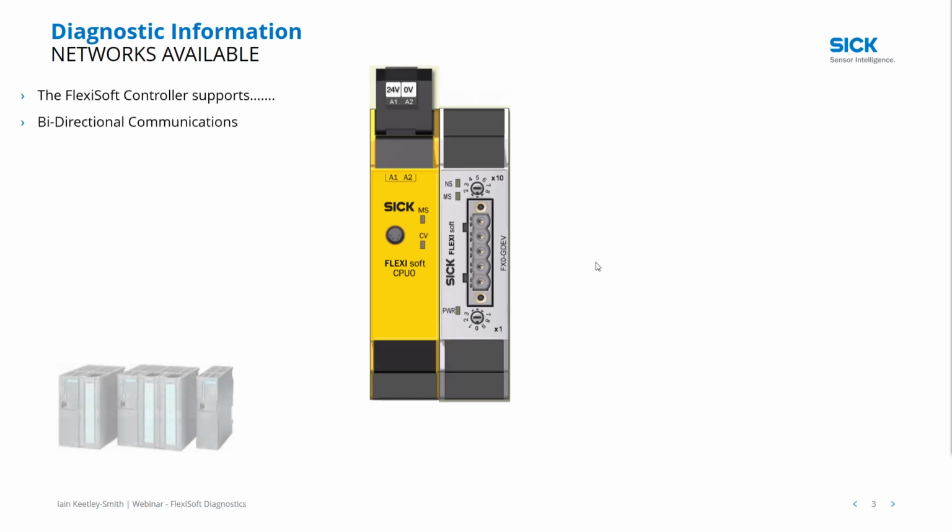So all of the gateways within the FlexiSoft Designer are bi-directional, so we can send data from the FlexiSoft down to the PLC, and we can also bring data back up. So data down, you'll see in the next slides what information we send down. But information coming back could be something like a reset signal or some sort of handshaking to say the PLC is running. So if the PLC isn't running, the safety won't run in, and things like that.